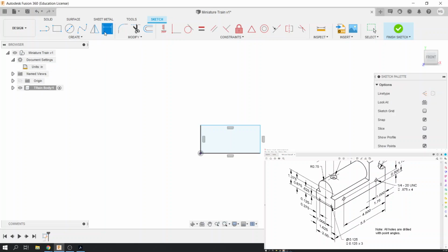I'm going to click on my dimension tool, and I'm going to make sure that this rectangle is 2 inches wide. Now I want to know, how tall is this rectangle? So I'm pointing at the height of the rectangle, and I'm following these extension lines out, and I can see where these arrows are pointing, and I see this little 0.875. That's how tall this rectangle is. So I'm going to click here. Okay, here to here, 0.875. Okay, there's the height of my rectangle.